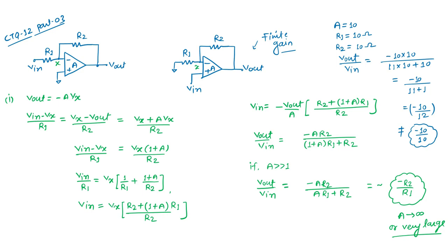Okay, and we can simply write the KCL equations, and one relation is directly that the output of the amplifier is nothing but the difference voltage times the gain. And what is the difference voltage? The difference voltage is V positive minus V negative, times gain A. So this is the gain expression we directly write every time.